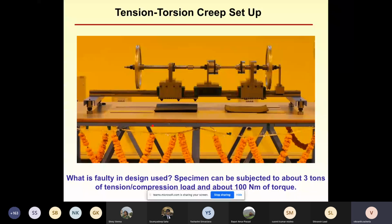Once we did that, this was working fine. Okay, so the moral of the story is that do not always be concerned about the strength and failure from either breakage or permanent deformation. Also, always pay attention to the change in shape that can happen in your system because of the loadings. Elastic deflections are as important as any permanent shape change in the parts. That's the moral of the story here.